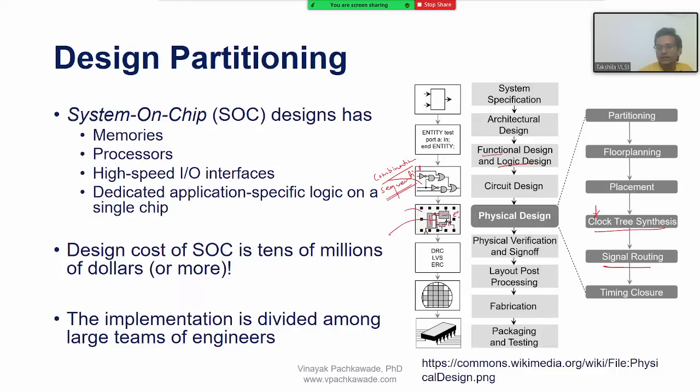As you can see, these signals are routed here. And the timing closure: when you have many flip-flops, many functional blocks, many latches, all are synchronized with each other through one word, which is clock. So you have to make sure the clock arrives to the particular function or the logic exactly at the same